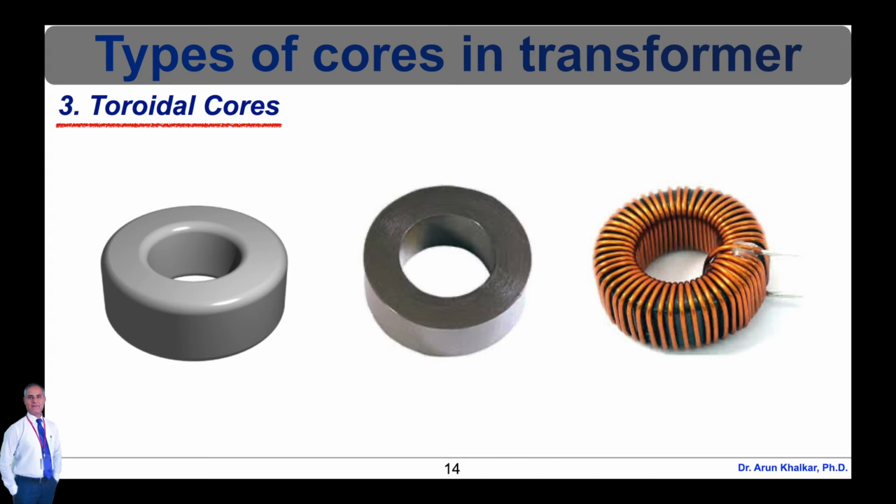Toroidal transformers are built around a ring-shaped core, which, depending on operating frequency, is made from a long strip of silicon steel or an alloy wound into a coil, powdered iron or ferrite. A strip construction ensures that the grain boundaries are optimally aligned, improving the transformer's efficiency by reducing the core's reluctance.